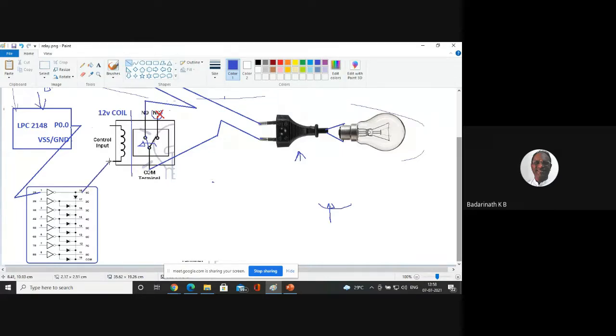It's very important: this ULN2803 does not generate a voltage. You should always remember, it can only amplify. It's only a transistor. So that does not mean that if you connect here, it supplies the 12 volts. No, that is why you should not connect to this point.